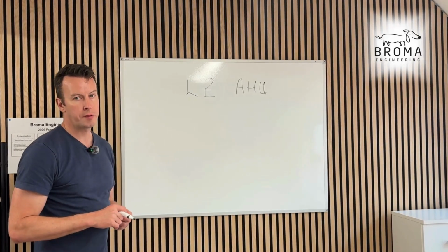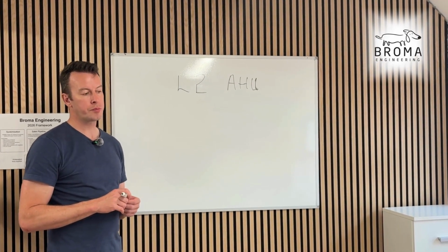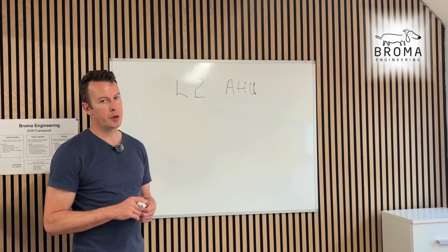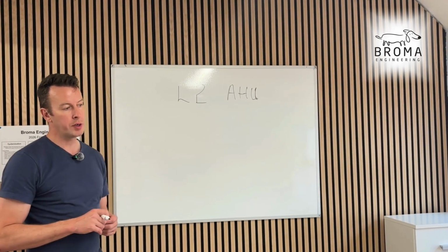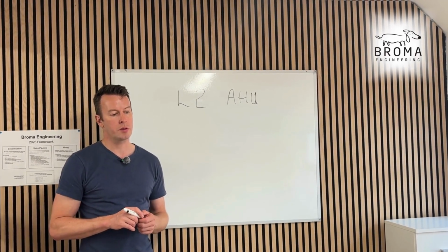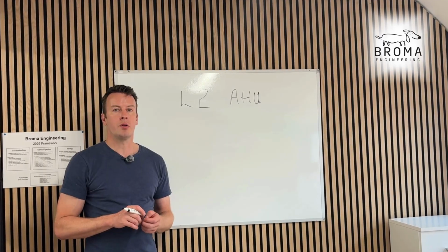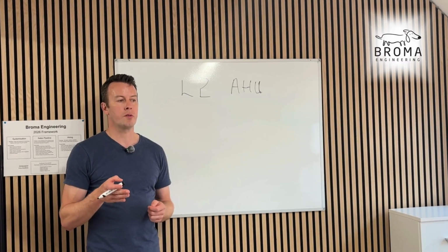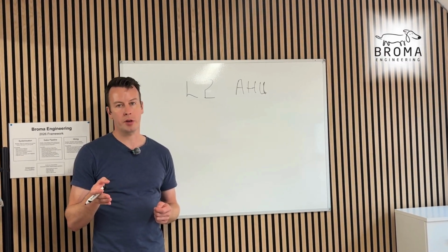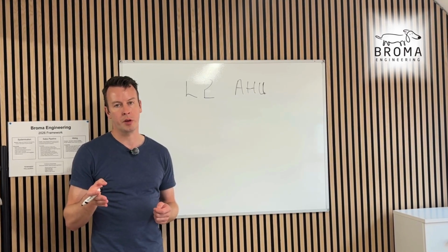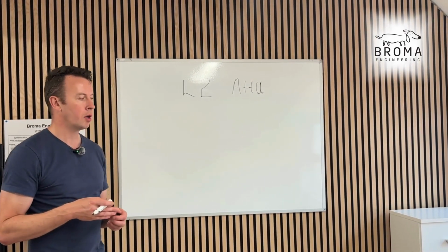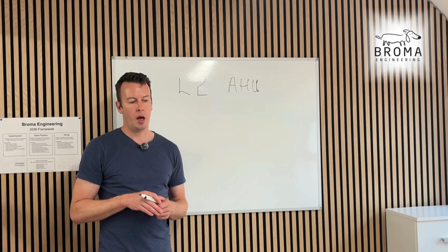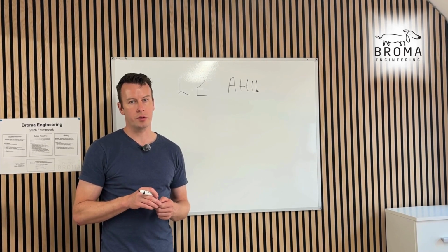So now we'll have to organize our walk downs. In a perfect world, we're holding the schedule, and these are in the schedule and spaced out in a way that's reasonable. So early on, I would have these in the schedule. There's a walk down, give time allocation for a number of AHUs, talk to people, make sure everyone agrees. The scheduler has it in as an activity, and we're getting ready for power on. That's the goal here now.